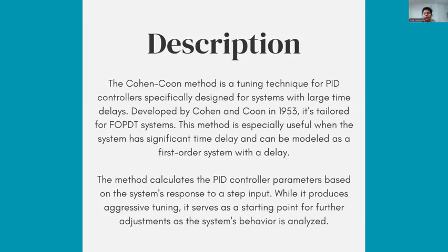For advantages and practical use, one of the most significant advantages of the Cohen-Coon method is its flexibility, unlike the Ziegler-Nichols method, which is limited to systems with short delays. Cohen-Coon can handle processes where the delay is up to twice the time constant. This broadens its applicability considerably. Moreover, it provides provisions for a PD controller, which is not something most tuning methods offer. That said, if the controller objectives prioritize robustness over speed, reducing the controller gain can help achieve better stability.